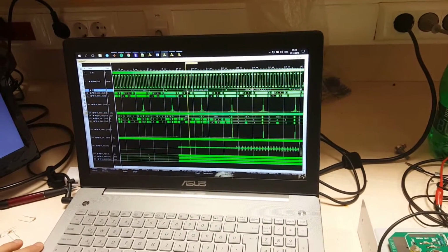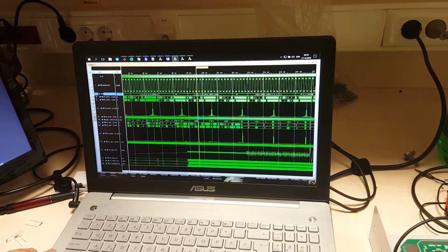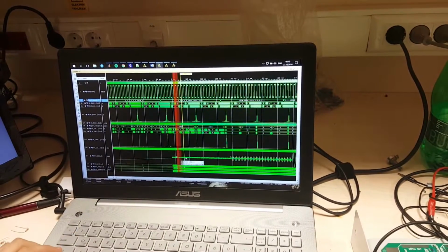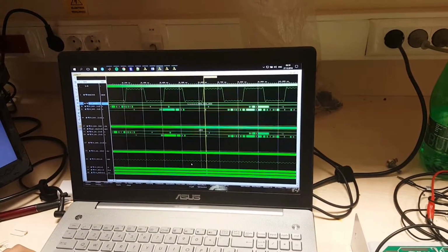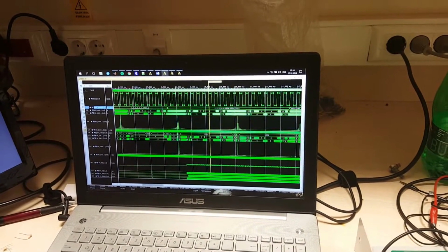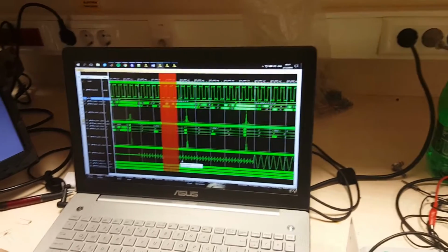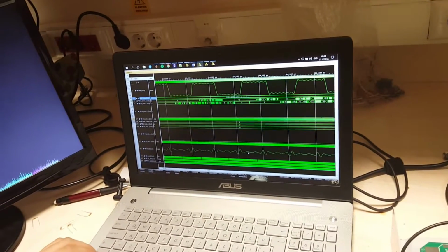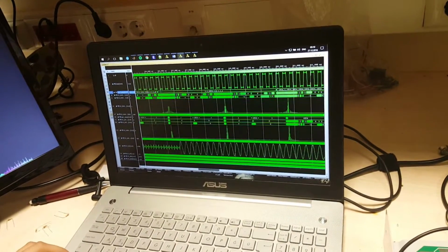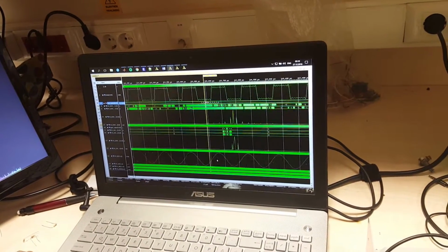These values here show my filtering values. First I apply a high pass filter. So my signal is filtered and only high frequency components are allowed to pass. So the resultant signal is this. After that I apply a low pass filter and my resulting signal is this, a pure sinusoid.